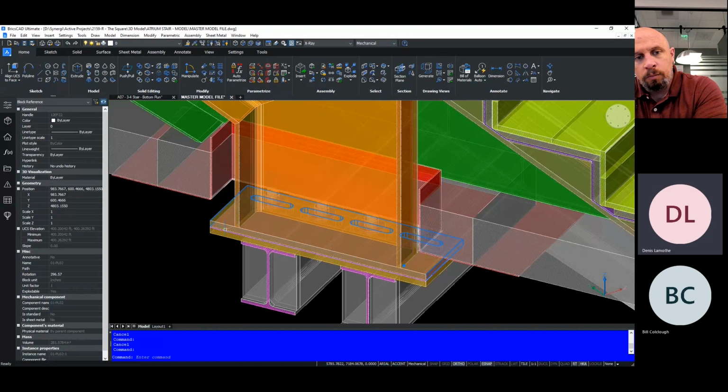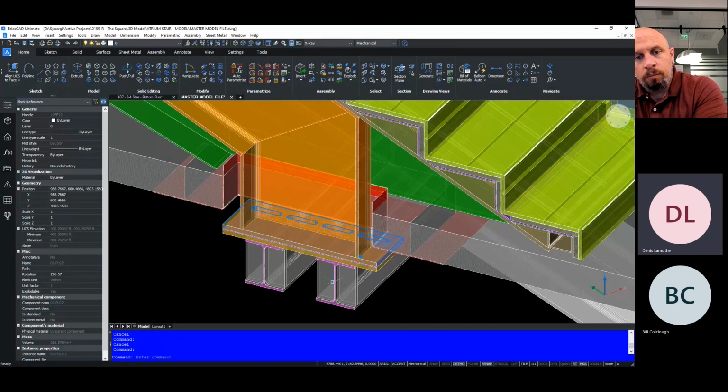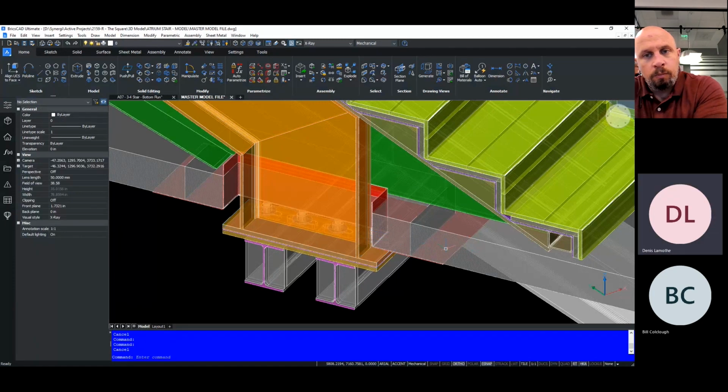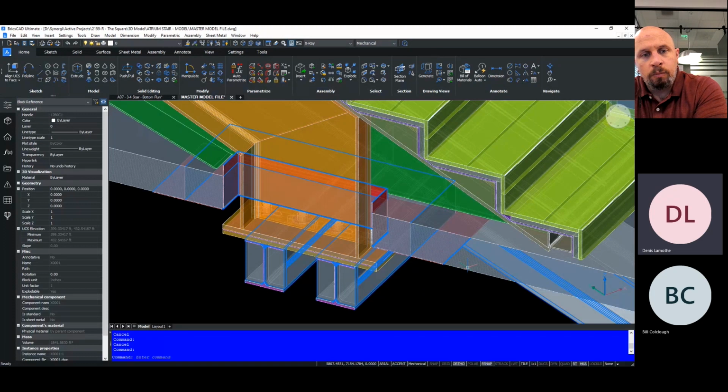But base plates will typically be bolted to either the structural steel beam below or the concrete slab. We have instances where, if we're really lucky, we'll have embed plates already in the concrete slab, and we could just weld the stringer straight to those embed plates.